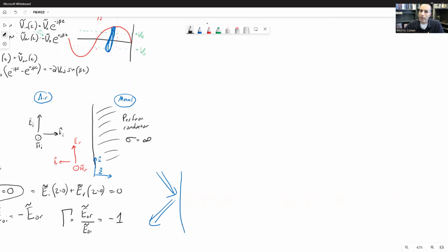There's no reason why you can't have a magnetic field inside a perfect conductor. But we do have a boundary condition, which is n hat cross (H1 minus H2) equals Js. Now here, we are going to make the assumption that since there is no wave propagating into the metal, and the electric field is zero, that must imply that the magnetic field is zero. So let's just define this for a second.